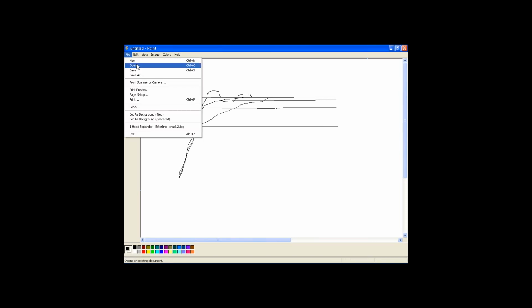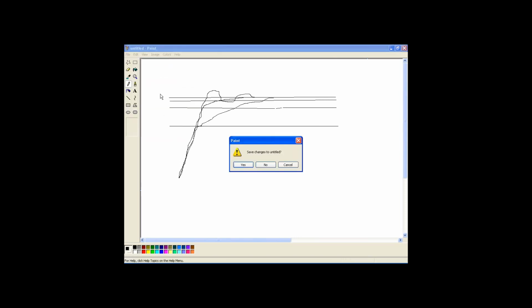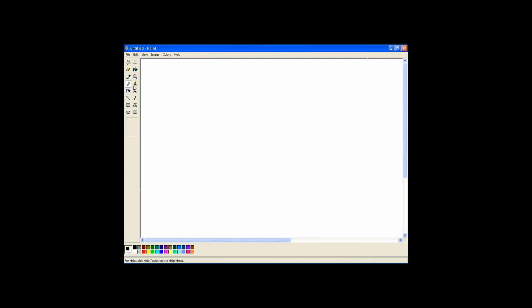So that proportional band gives you the ability to decide how hard you want the chamber to drive, or how close to set point you want it to drive before it starts backing off. So the classical reason to adjust this is if you're getting too much overshoot, where you want it to start backing off quicker, or you're seeing it's just taking way too long to get to set point and you really don't want it backing off so quick, then you can adjust that.